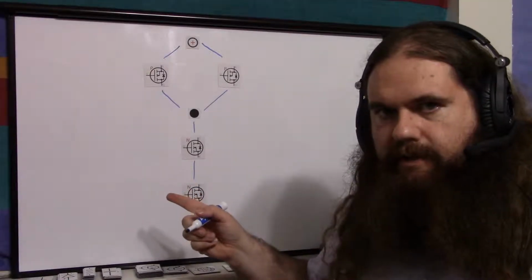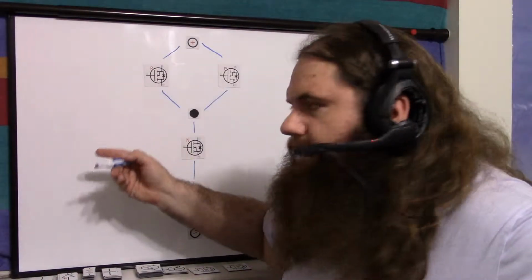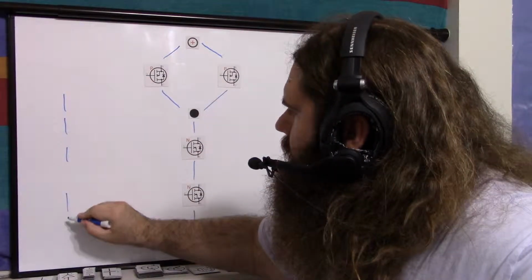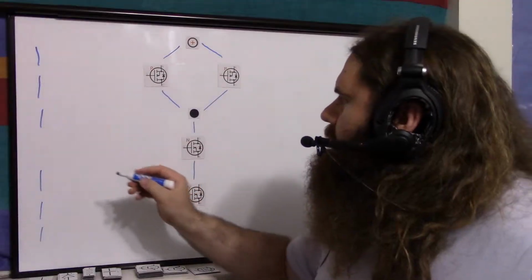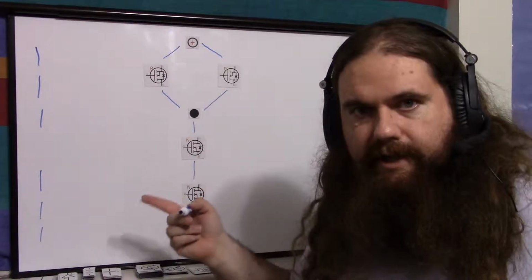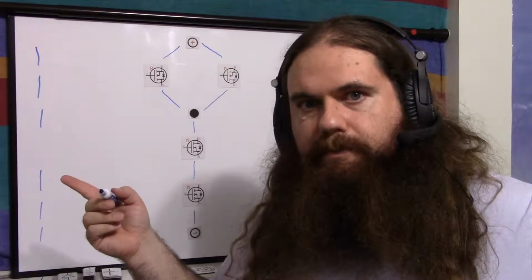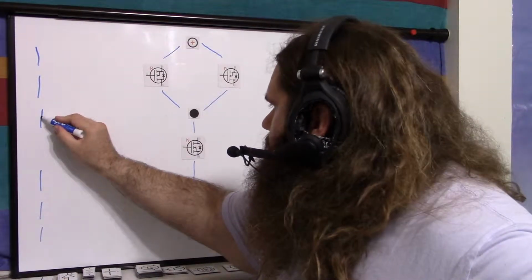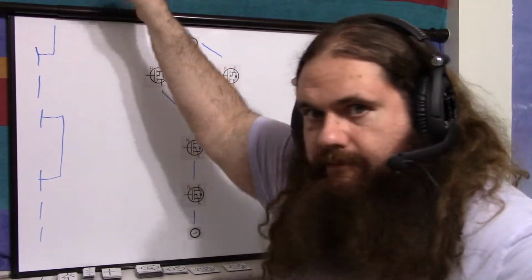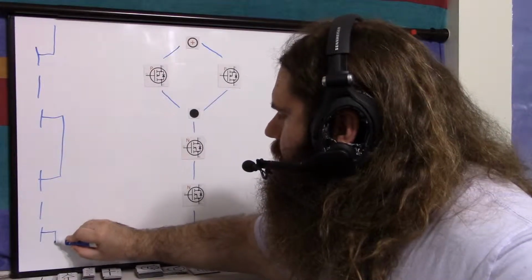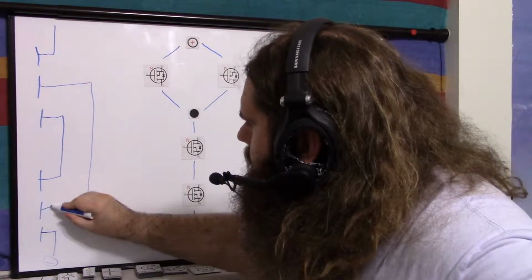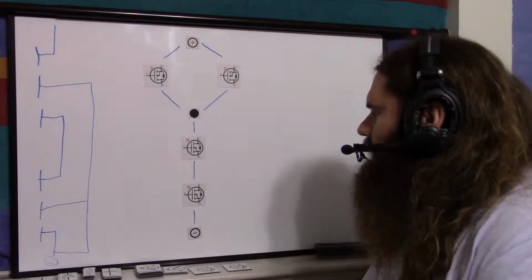Now, regarding the notation, you'll see some places when they denote these transistors in series, you'll have like your 3 lines on this one and 3 lines on this one. Let me draw this a little higher. So what you'll have, remember, this is the drain, the substrate, and the source, and the substrate and source are tied together in discrete ones. Well, when you're doing a chip, they're not tied together. So you'll actually take the source of one into the drain of the other. Then the drain of the first one is getting its input. And then the source of the last one is connected to your negative. And the substrates are all grounded as well out to this negative.